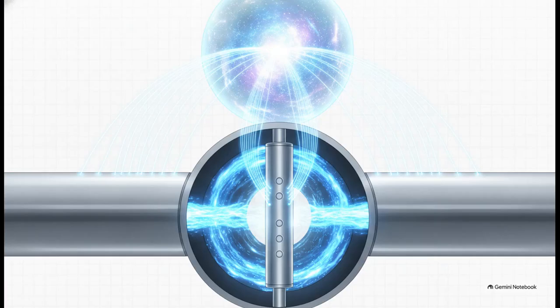One really fascinating application of Bernoulli's principle is the Annubar. The Annubar harnesses this exact physics, but it acts as an averaging pitot tube. It measures liquid, gas, or steam flowing through a pipe by sampling the velocity across the entire width of the pipe, comparing the difference between the total pressure and the static pressure. It's a real game changer because it allows for highly accurate volumetric flow rate calculations without having to cram a massive restriction plate inside your pipe.